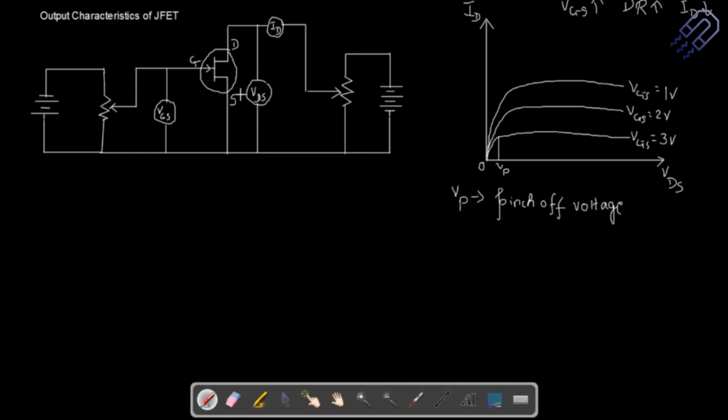Also remember the tap analogy that I've given you, and based on that we can understand that JFET works on a similar principle. If we look into the output characteristic, which is important because how it finally behaves is more important here, we can see that if we are varying the gate source voltage, for example increasing it, the depletion region is going to increase in width.